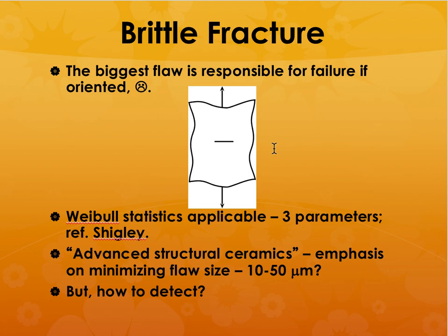So there is a lot of spread. Now, what is the probability that your sample will break at 10 KSI? It's going to be extremely small because maybe only one sample broke at that number. And at 90 KSI also, you may have only one or two samples that broke at that value. But most of your samples would have broken at the average value. So you will have a higher probability for your sample to break at 50 KSI than at 90 KSI or at 10 KSI.